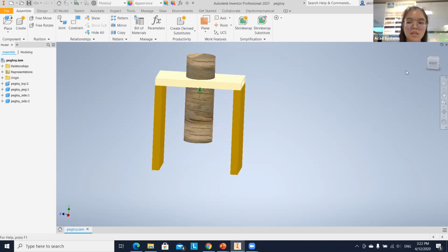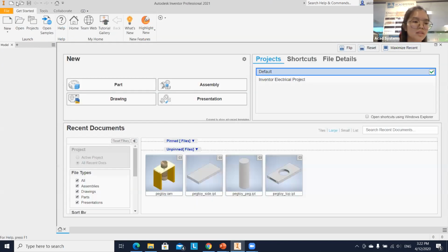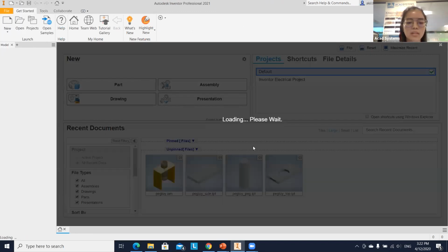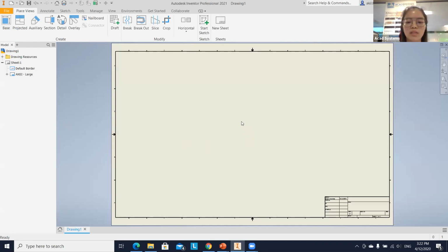Now we'll save. And then we can close our assembly. And now we are going to create a drawing. Same process, drop down, click drawing. Just notice, right, when we come in that the drawing itself, it's a D size paper, so it is quite big. If you're planning to print this out on a home printer, what I suggest to do is just to delete the title block, select and then delete.